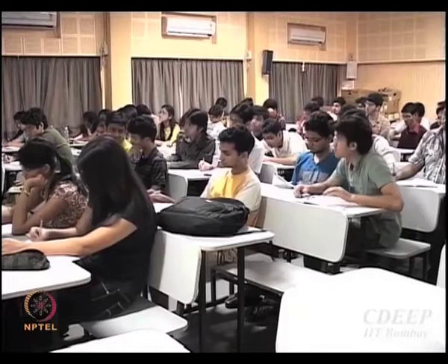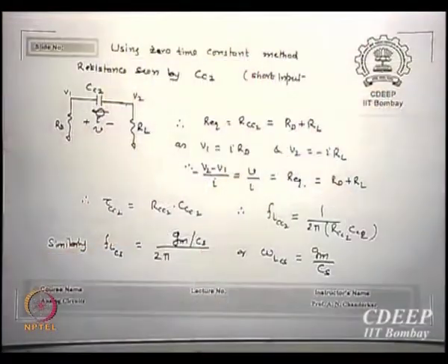How much will be CC1? What will CC1 see? Same method, tell me from your figure how much it will be. RG plus R signal, that's the only resistance it will see. These methods are not so common in the books. Of course you can go and read the books, any of the four I gave. They are a little more rigorous, maybe putting in some arrows, looking at the GM equivalent. Finally what they get is what I am getting without doing all that. That's the way I do it.